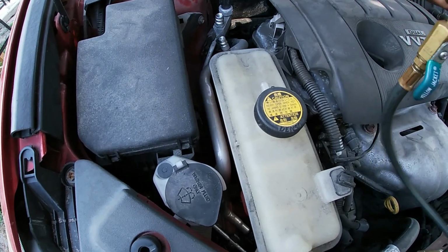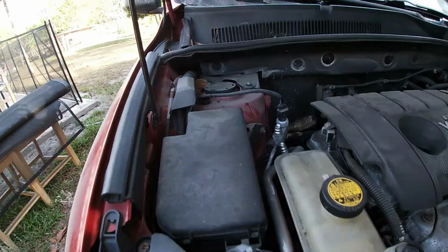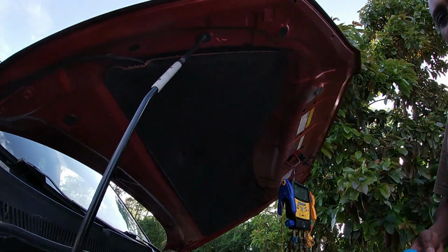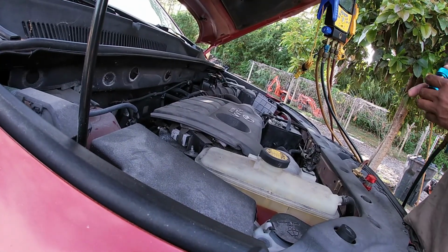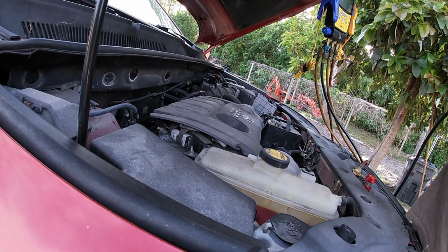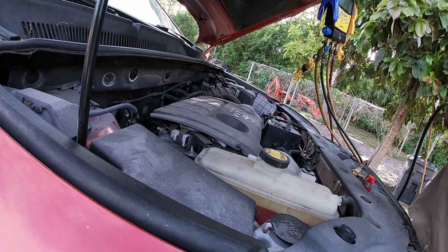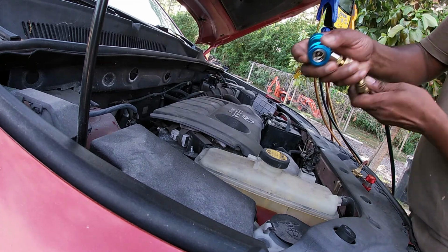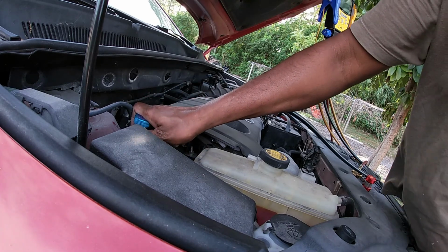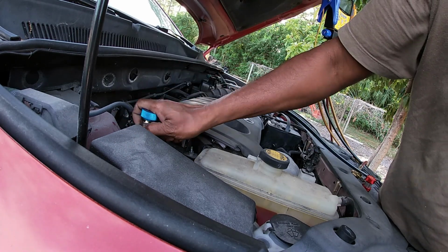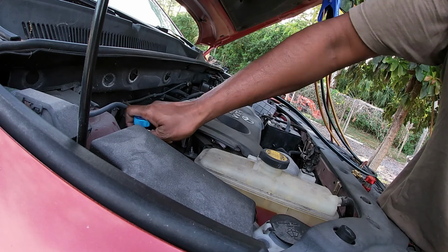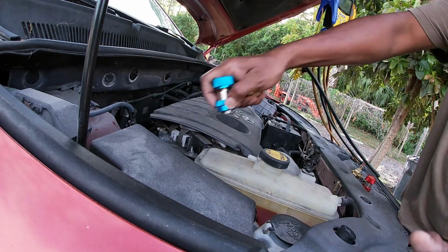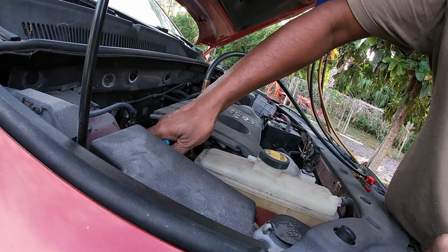This sensor can cost anywhere from $10 to $50 depending on who wants to rip you off or not. The dealer does not replace the sensor, it requires the entire compressor replacement. And to get the sensor off and on from the compressor, you need to pull that entire compressor off the vehicle, and to pull it off is not an easy job.